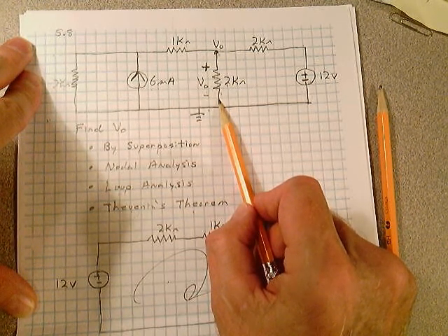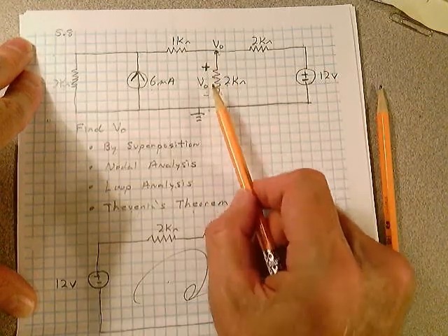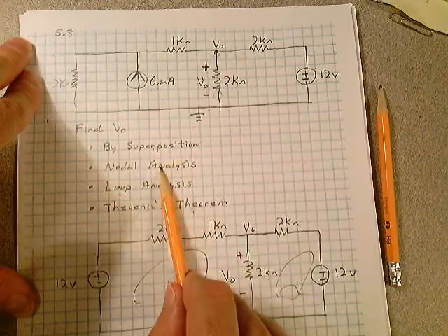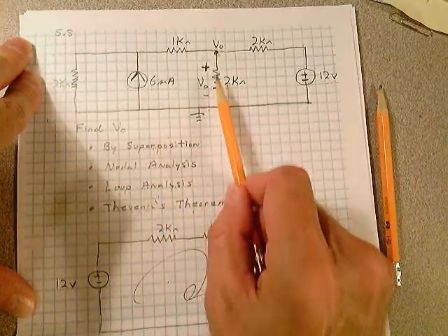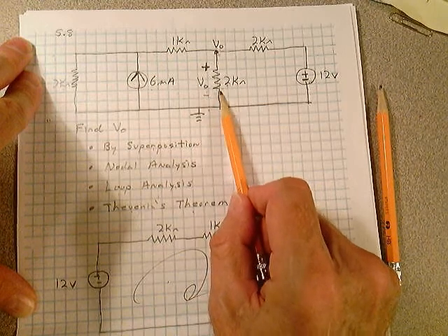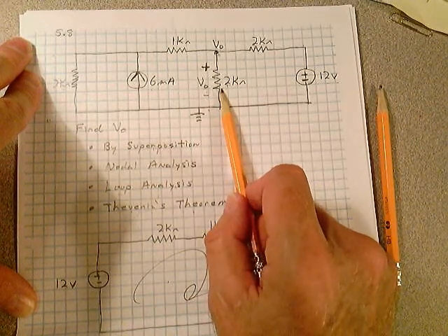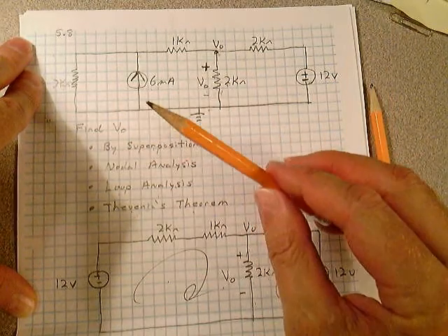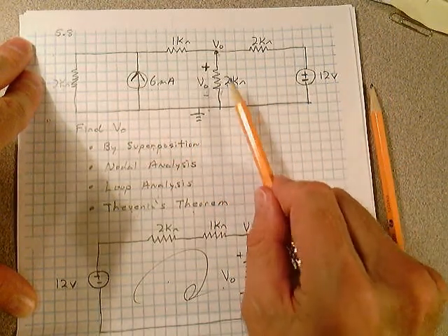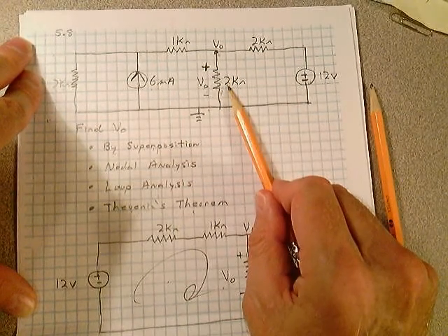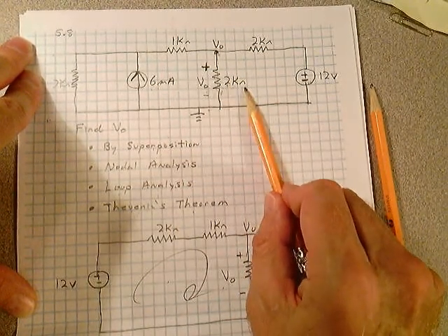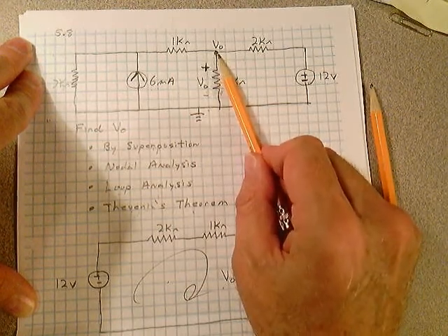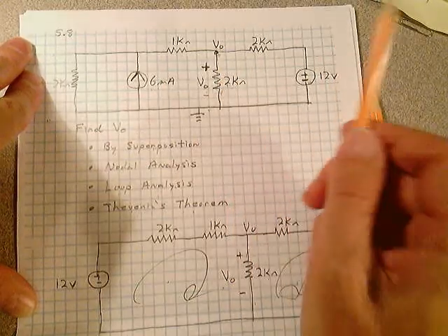Once you do that, it's okay in that problem to use this as a tool. You're working Thevenin's theorem, but you might need this or this or this as a tool to find that open circuit voltage right there with that 2K resistor removed. Once you find that, you find the Thevenin equivalent circuit. You find E Thevenin. You already know R Thevenin. Don't forget to put the 2K back on. Students forget that. You put the 2K back on, and you find what V out is. 7.5 volts.